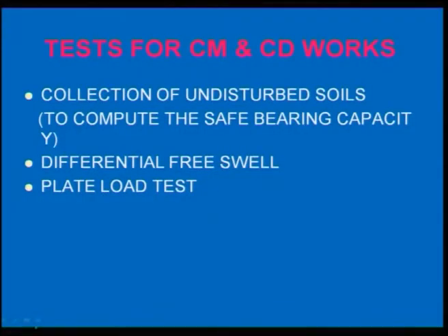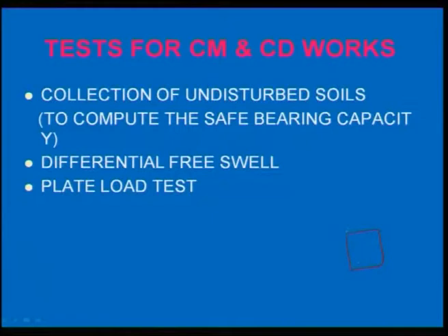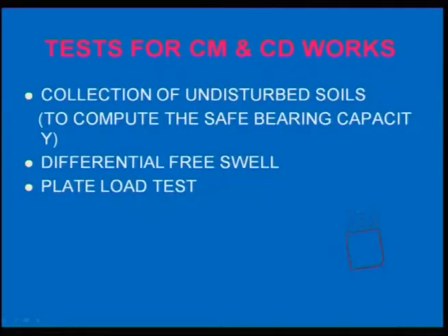Free swell test means, particularly in an irrigation project, where the soil sample is there, what will happen during the summer season is that it will try to shrink. During the winter season, as water is added, the soil will try to swell against loading. Sometimes we say free swell or swell against the surcharge. That means with the application of water it will try to swell. This is most important, particularly for irrigation projects.